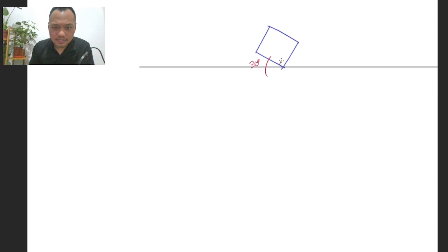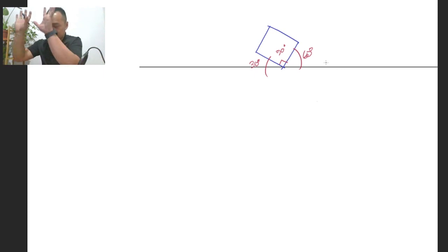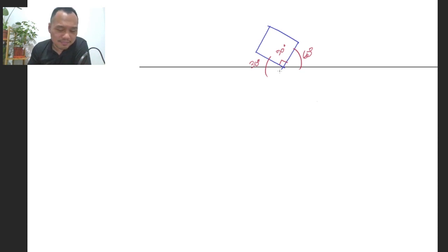And so if this corner right here is 90 degrees, a perfect right angle, then this one opposite side would be 60 degrees, right? And the reason we rotate it that way is so that the viewer can see. So like I said, this is our picture plane line, so imagine it as what we're seeing. If we only have the one face resting on top of the picture plane line, what we end up with is a distorted elevation, basically, which is what we don't want.